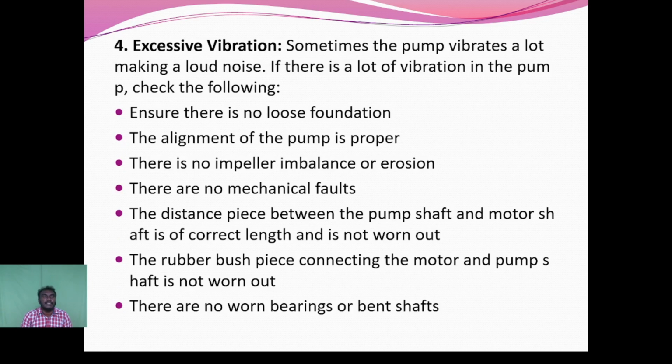The fourth one is excessive vibration. Sometimes the pump vibrates a lot, making a loud noise. If there is a lot of vibration in the pump, check the following things. First, ensure there is no loose foundation. The alignment of the pump is proper.